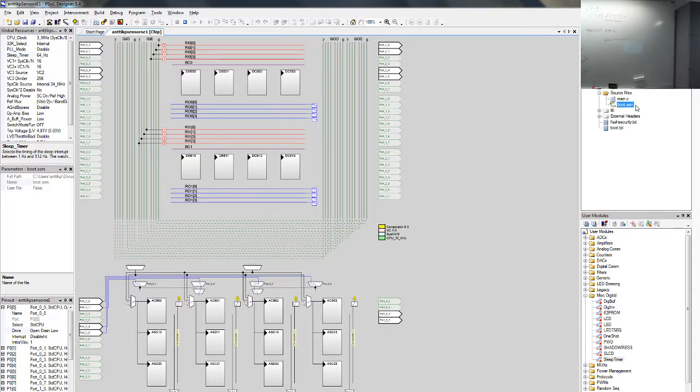Okay, so it's always basically the code starts from the boot section, which is nice since you have done some assembly programming, and every single assembly program starts by initializing the processor, the environment. You have to put the code there to basically select some clocks, rates, and fundamentally the left hand side corner, whatever you select on that global resources, that will actually end up being code in your boot.asm.